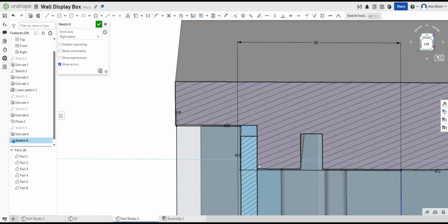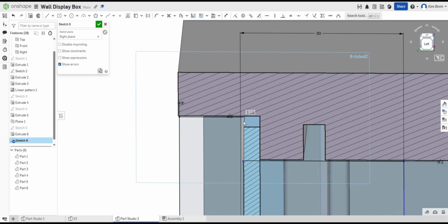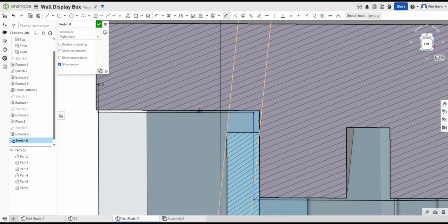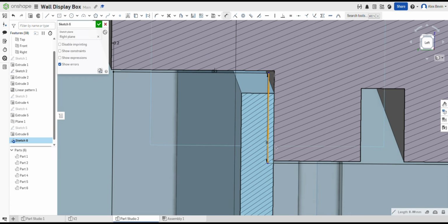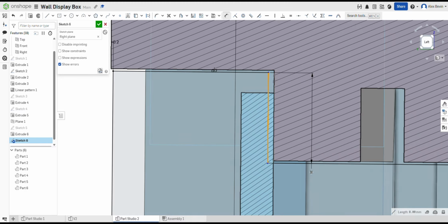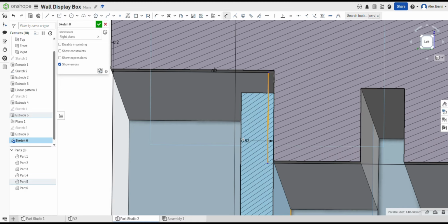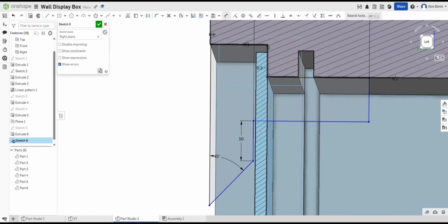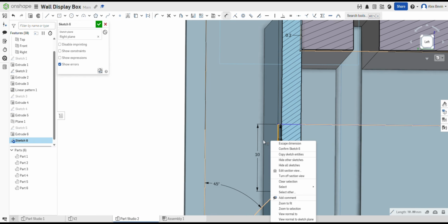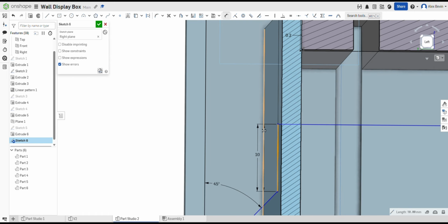This is 10 millimeters. Now the cleat thickness. The profile thickness is 8 millimeters. And now we add clearance. Because this is a printed-to-printed cleat, and we want a looser fit to allow for small inaccuracies, I'm adding 0.2 millimeters clearance. In this example, I'm applying that clearance around the edges of the profile so the cleat doesn't bind